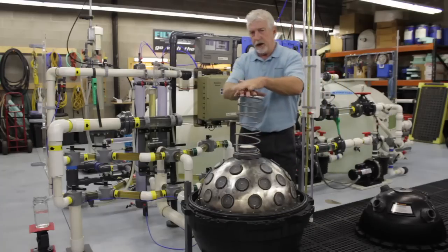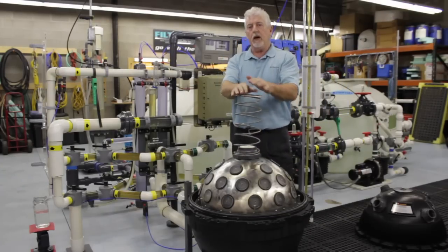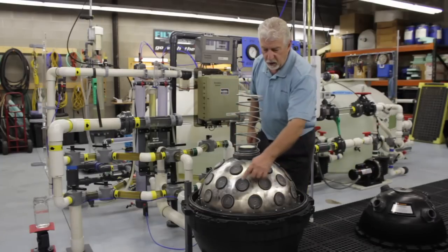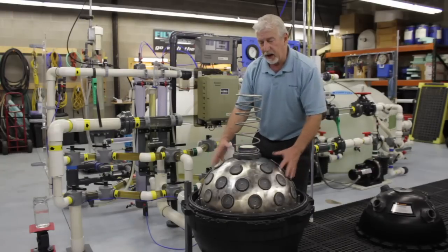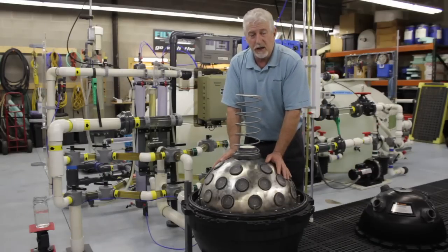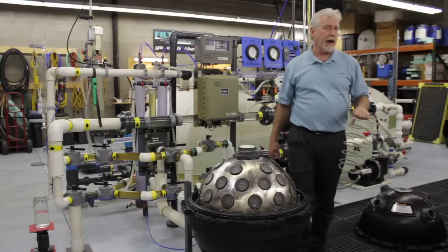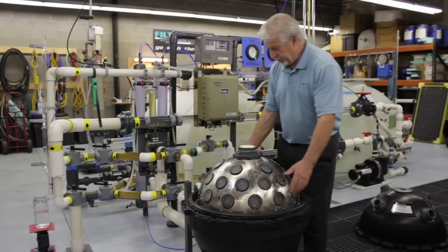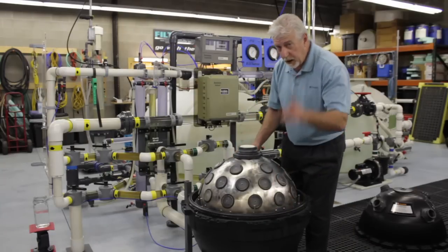Now, in the filtration mode, there's a spring that's putting compaction pressure all the time, whether there's flow or no flow, onto the media, holding it at minimum void. During filtration, these little holes here, which were calculated by us, put a delta P as the water goes from the outside to the inside of the container. That adds additional force, which is actually in the tonnage. Now you ask, how does it go up and uncompact in the backwash cycle? When you reverse the flow, the delta P is backwards, and it actually overcomes the spring and lifts this up all the way.